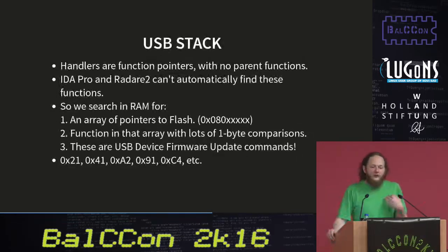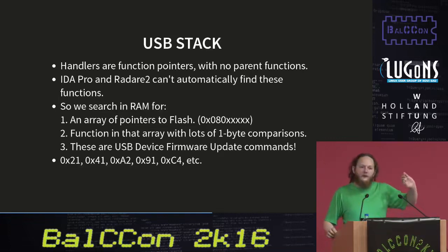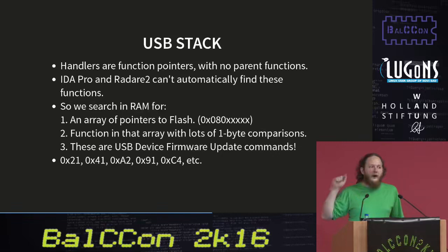It's also handy to reverse engineer the USB stack. So the USB stack is by a different author than the audio codec and the main application. They used a nifty trick here, which was that they took the example USB stack from the manufacturer and then reused that. Well, when you do this, the source code is available. So unlike the rest of the radio, you can actually go to ST Microelectronics' website and get a copy of the example that was forked for this project. This then tells you how it's architected, all of the data structures, it gives you the header files. It's lovely for reverse engineering.